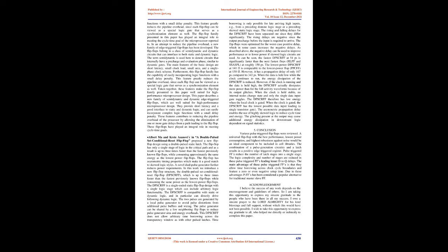These features contribute to reducing the pipeline overhead of the processor by allowing the elimination of one or more gate delays from a path leading to the flip-flop. These flip-flops have played an integral role in meeting cycle time goals.